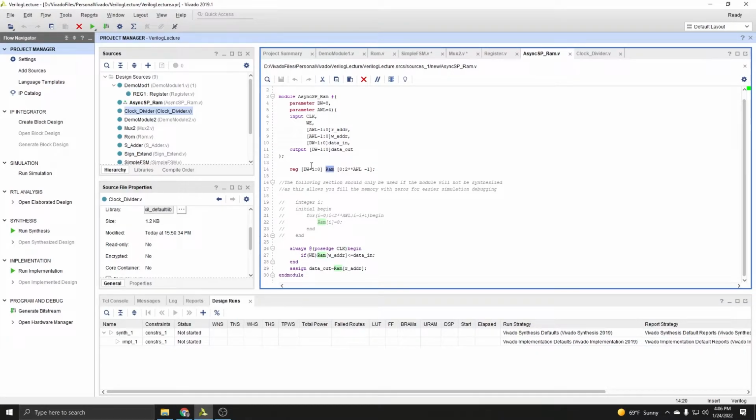So most memory locations are going to have the number of locations correspond to the number of bits. So just simply do this method here of 0 to 2 to the power of the number of bits minus 1. Now, when you do this, keep in mind that you don't want to use an address width that is too